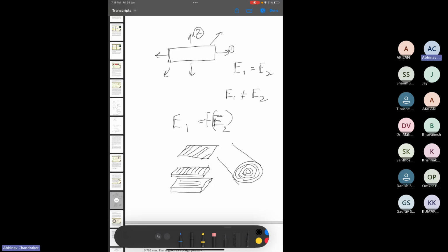And since you are just using a rectangular cross section of it, something like this, you can assume that on an average the material will behave like a superimposition of all of these different layers having fibers oriented in different directions. And this particular thing is called an orthotropic material. Exactly what are the details of the symmetry that you observe for this material, you'll have to look up in more detail. But for our context, I think this much should be enough.